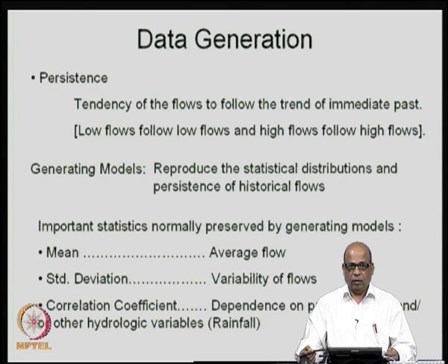So, the generating models reproduce the statistical distributions and persistence of historical flows, when we are talking about generating models for the flows. As I just mentioned, we have the historical data for which you would have calculated parameters such as mean, standard deviation, correlation coefficient, and several other moments and statistical parameters. So, we develop models for data generation, which when used will reproduce the data, which will